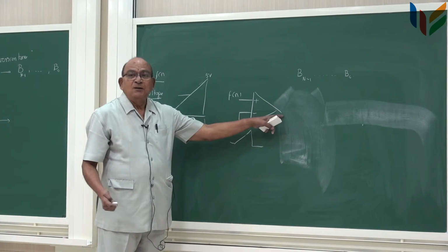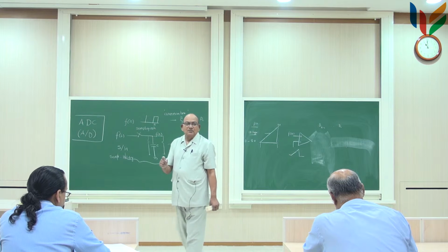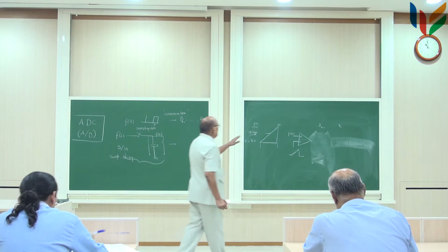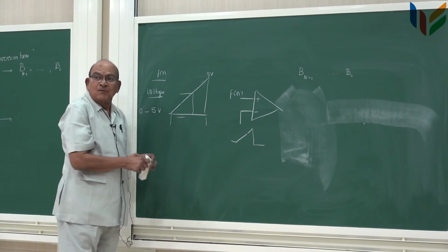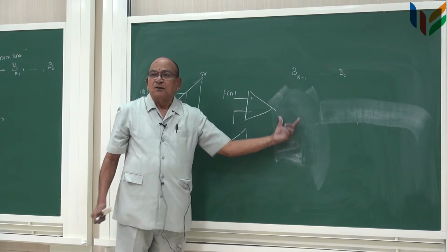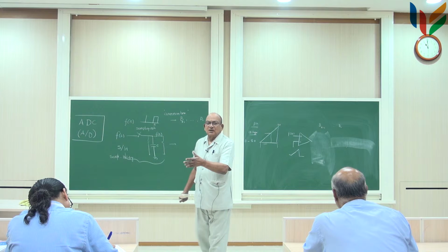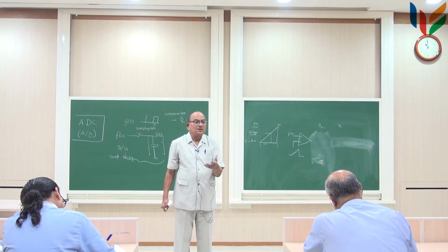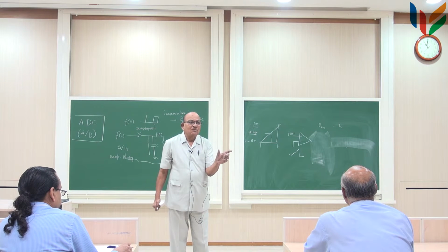So you know when the values are equal, and that is the time you have now converted that 5 volts or 3 volts into a corresponding time. So the pulse width you get here, from the original state to the other state after the comparator gives the change in the state, will give you the width of the time. Are you with me or not?